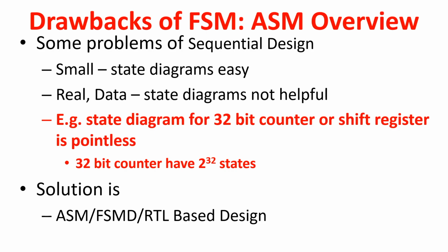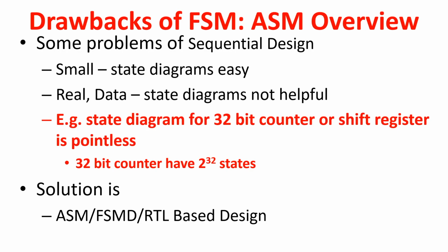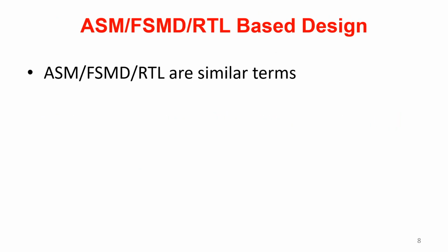So, we include registers for storing data, that means we separate the memory elements, particularly the data path, memory elements and the actual compute unit, out of the state machine. All three terms, ASM, FSMD and RTL based design, are similar things.